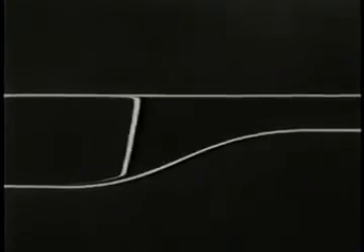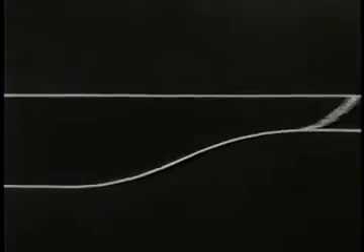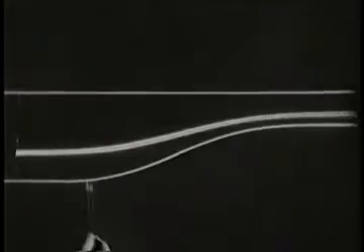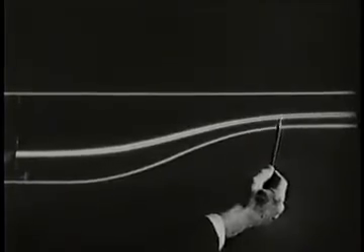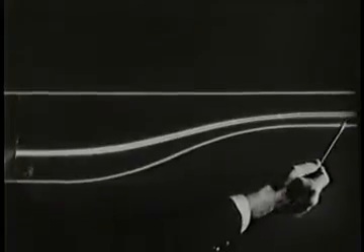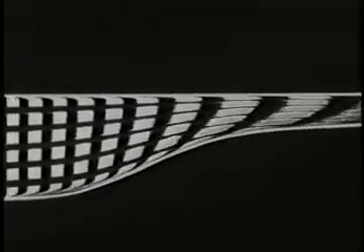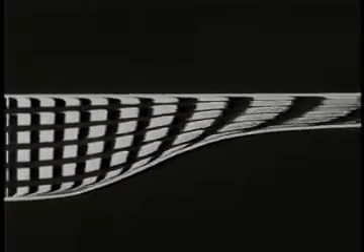Here, near the beginning of the curve, the increase of stream tube area between the streamline and the curved wall shows that the velocity on the curved wall at first decreases. Near the end of the curve, the stream tube area reaches a minimum before once again increasing slightly. This minimum corresponds to the point of minimum pressure. Where the pressure rises on the curved wall, the viscous boundary layer thickens. If a rising pressure gradient is severe enough, the boundary layer might separate, or a laminar layer might become turbulent.